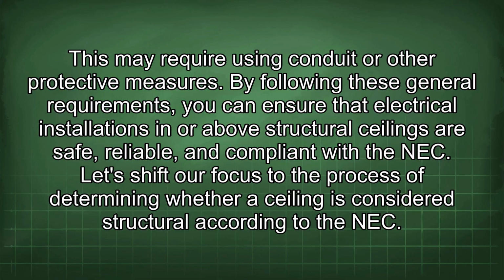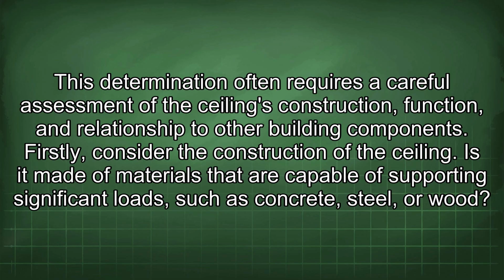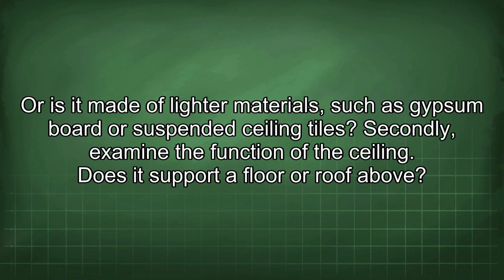compliant with the NEC. Let's shift our focus to the process of determining whether a ceiling is considered structural according to the NEC. This determination often requires a careful assessment of the ceiling's construction, function, and relationship to other building components. Firstly, consider the construction of the ceiling. Is it made of materials that are capable of supporting significant loads such as concrete, steel, or wood? Or is it made of lighter materials such as gypsum board or suspended ceiling tiles?